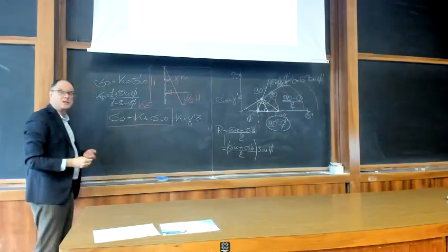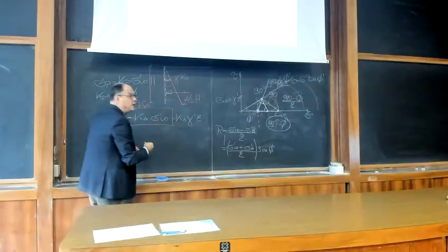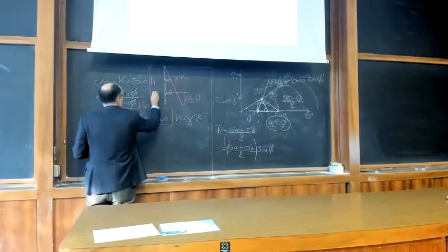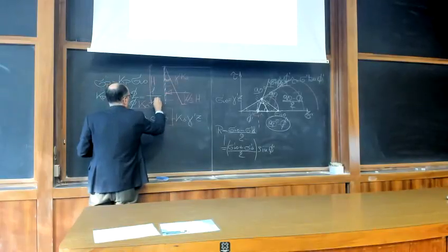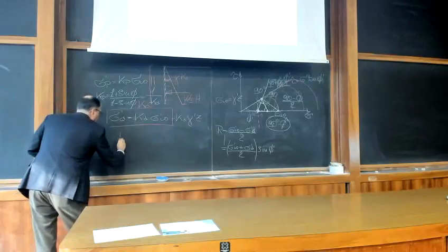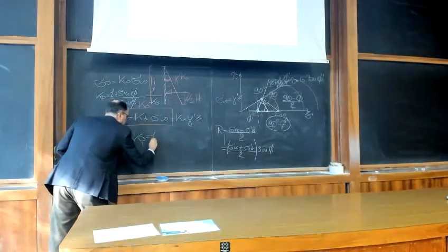And it is easy to check that according to Rankine theory, which is of course very simplified because reality is not exactly like that, this is exactly the inverse of Ka. So in other terms, you can also say that Ka times Kp is equal to 1.